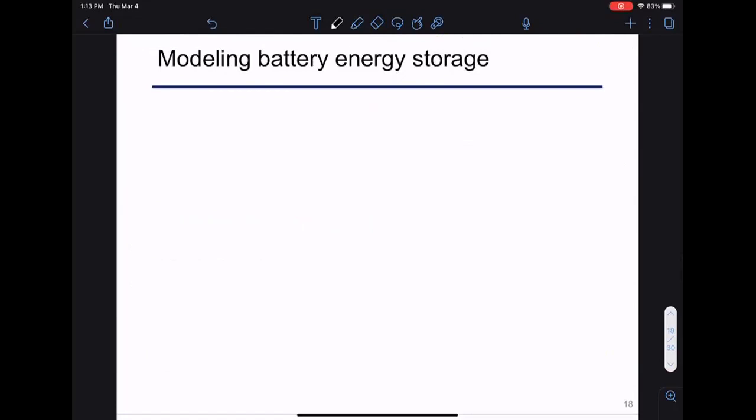If you buy a battery technology and you want to model it in the system, you have to put it in as a model. If you want a battery, then it has to appear as some component in the system. If it's generating power, it may appear as a generator. If it's consuming power, it may appear as a load in our optimization problems. So the normal modeling for a battery is the following. Normally there is no minimum generation, minimum load, startup or shut off constraints.